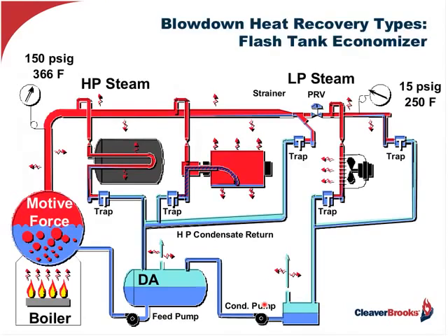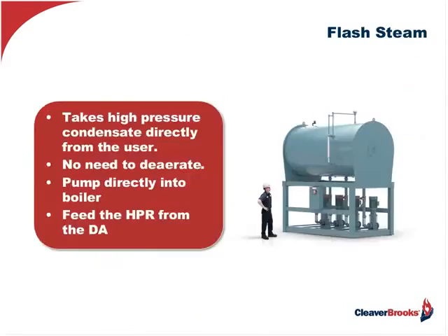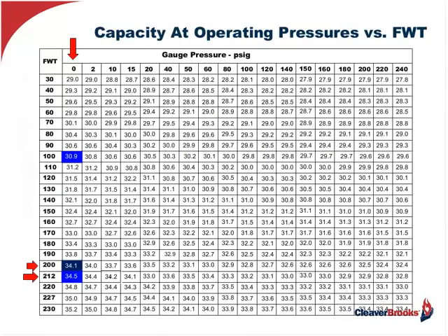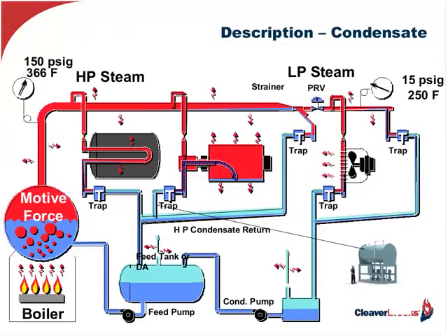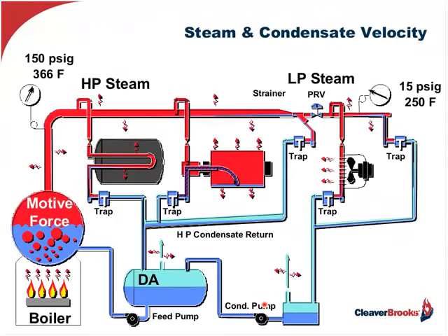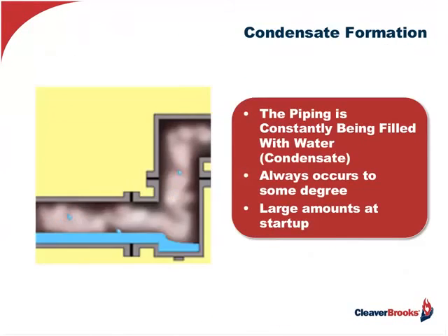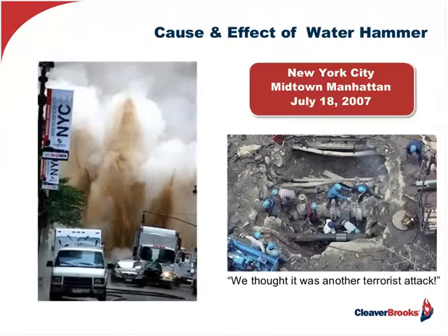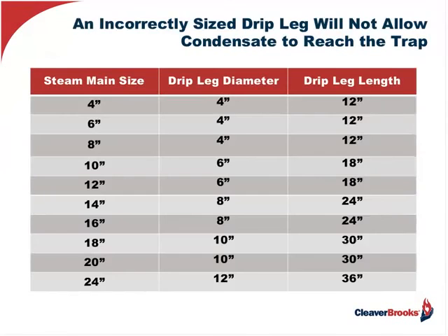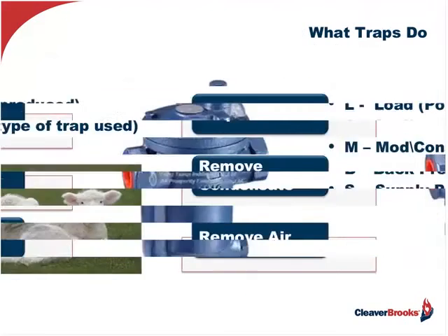And that's referred to as stall, S-T-A-L-L. This means you're losing the differential across the trap body, probably because of a modulating valve, and that's exactly what you see here. I've got a modulating valve, so I'm losing my differential, which is varying the inlet pressure to my trap.